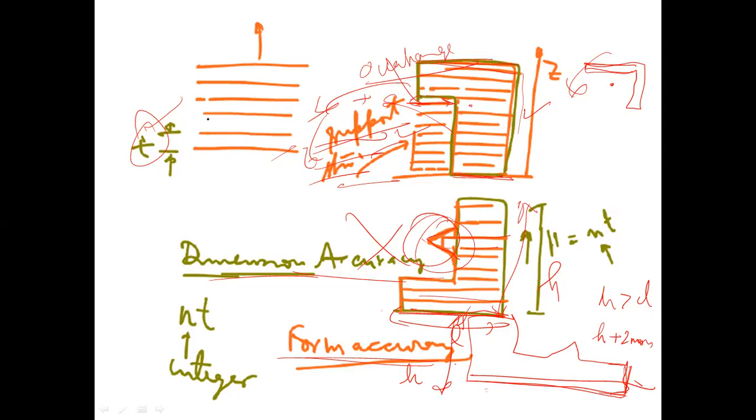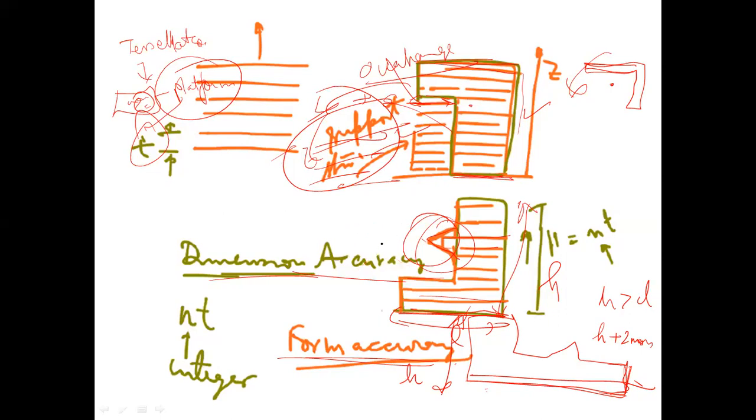So as you might have known by now, you do tessellation. Now, once you do tessellation, you have to put the part on the platform. So how to put the part on the platform? What should be the layer thickness? This is the criteria that we are discussing. So support structure generation again is something which is very critical to be decided at this stage itself, whether you want the support structure or whether you don't want the support structure. And if any product has features, then how to save that feature from getting ruined.